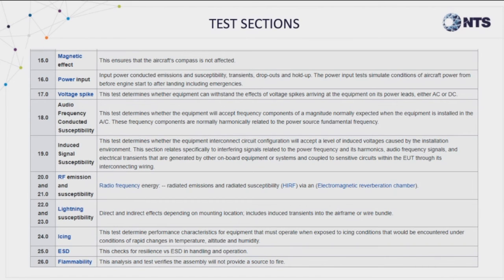your location. What determines the scope of the testing, I see the question coming up, is really, like I've been saying, what the part does, in terms of functionality within the airframe, where it's located within the airframe, and all those parts come into play. Usually that's an agreement with the certifying authority. You'll get a test procedure that says, here's the test plan, here's the test we intend to run, here's the criteria we believe we fall under, and you would present that to the FAA for approval. And when you gain that approval, then that would be the testing that you would go and apply.